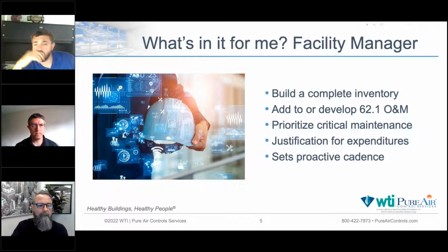And then, of course, the situation we see pretty commonly is the closure of dampers. We just had one of our test and balance assessors doing an inspection on a pretty large unit, the kind of unit that is taller than he was, and he had to use his foot to open the door of the air handler because the suction, the pressure, was so great.